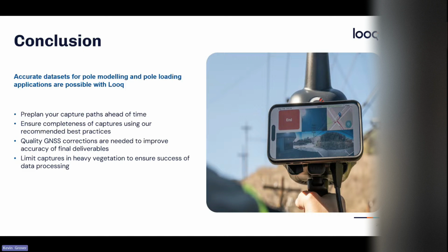Wrapping up, in conclusion, here are the best practices on your side to get the most accurate pole modeling and pole loading, and survey quality data for overhead utilities. Of course, pre-plan your capture. That's one of the best things we can plan out ahead of time: make sure you know how many captures you're going to be able to do, and that you've got the proper overlap.